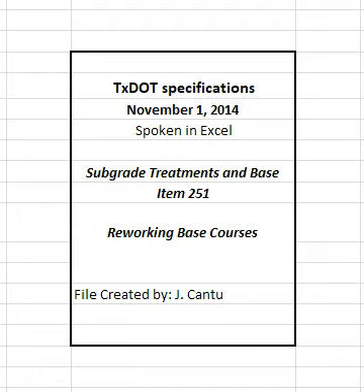Before scarifying, clean the existing base of objectionable materials by blading, brooming, or other approved methods, unless otherwise shown on the plans. Perform this work in accordance with applicable items. 4.1 Types of work. 4.1.1 Type A: Scarifying only. 4.1.2 Type B: Scarifying, salvaging, and relaying. 4.1.3 Type C: Scarifying and reshaping. 4.1.4 Type D: Refinishing. 4.2 Performance of work.